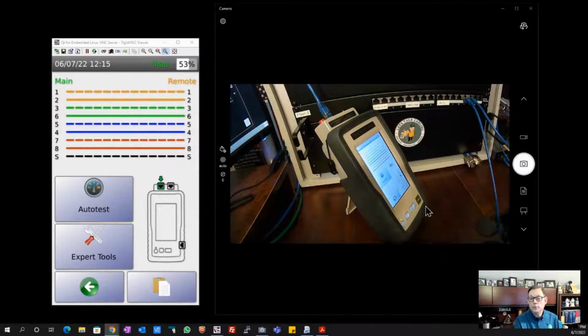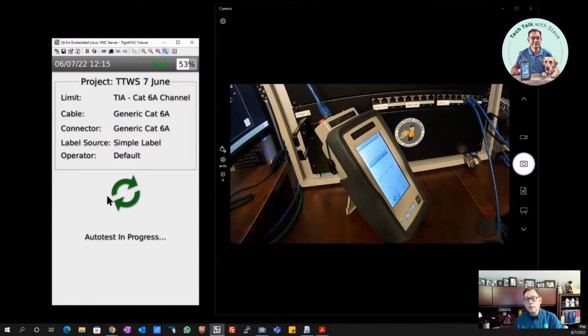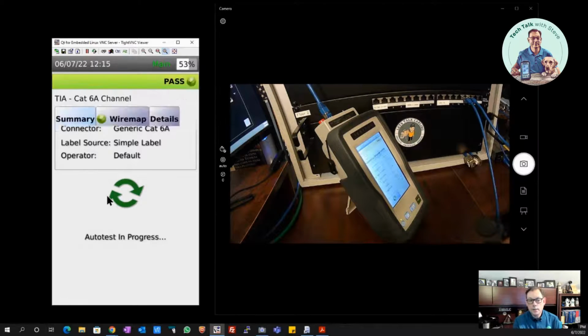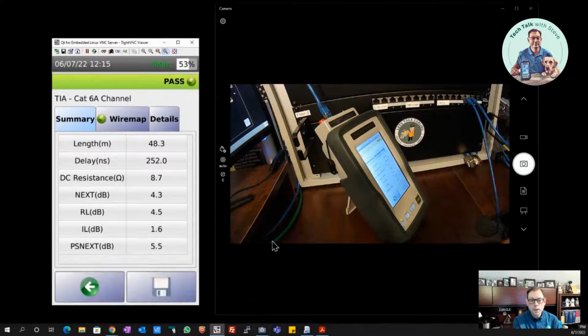In this case, we're going to do a physical cable test. So we know the wire map is good, and we can go ahead and run an auto test. So I'm just going to go ahead and hit auto test here. And the auto test will give us a result in 6 seconds. And at the end of that 6 seconds, we see this passed. We've got our Cat 6A channel, everything passed.